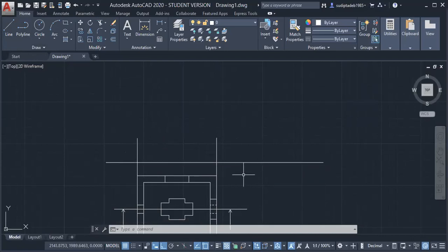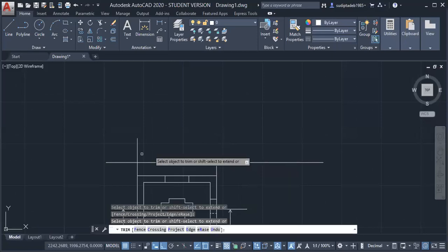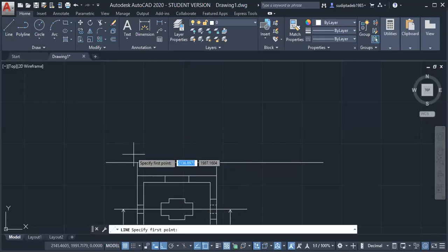So one thing we have to understand is that it will always start from the reference line, because the object is lying on the plane, so when you see the front view, we cannot see any deviation from the reference line. So we have to start our drawing from this point directly. So I am using trim at this point. Now I will draw everything from here.